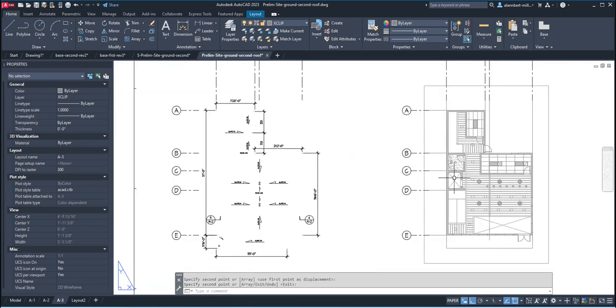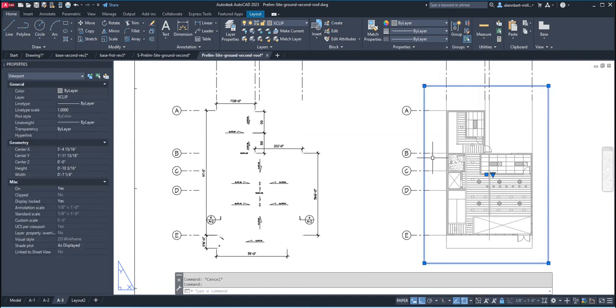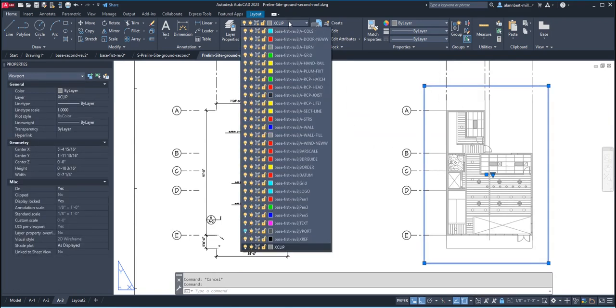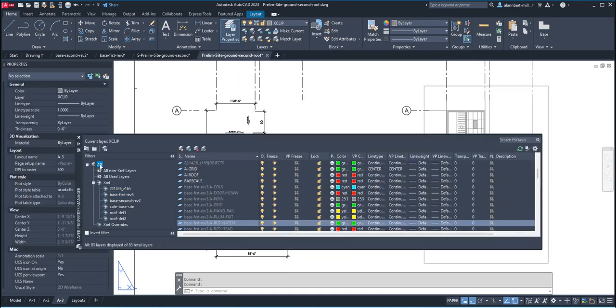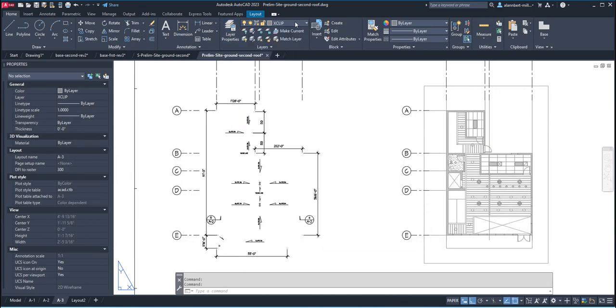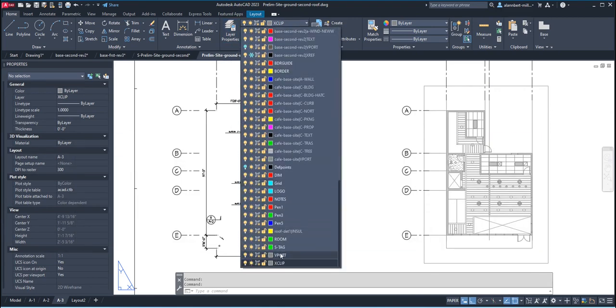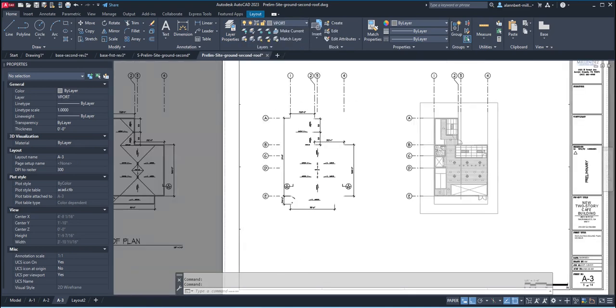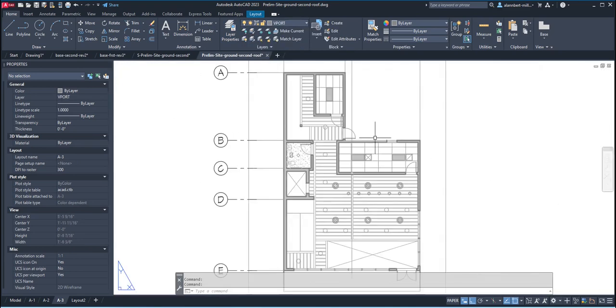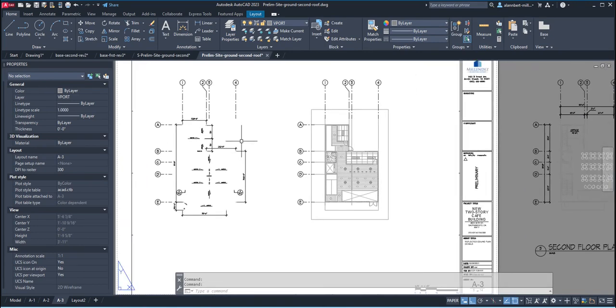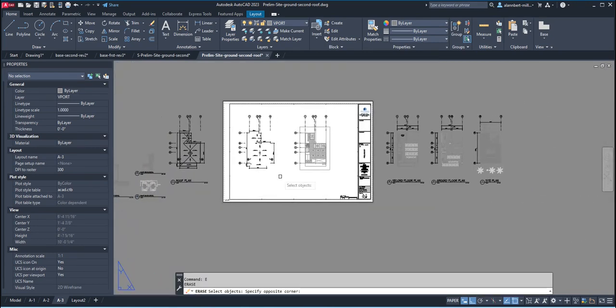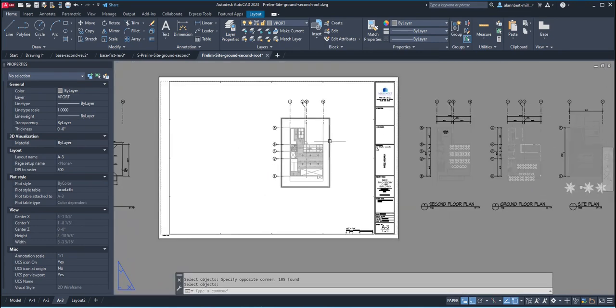Okay, and that's it. Okay, this is a viewport, so I'm going to click this one. I need to put this on layer viewport. Oh, I have to click my all layers and then close it so I can put it on the correct layer viewport here. So I can turn that off. Okay. I think that's it. I'll erase this because I don't need that anymore.